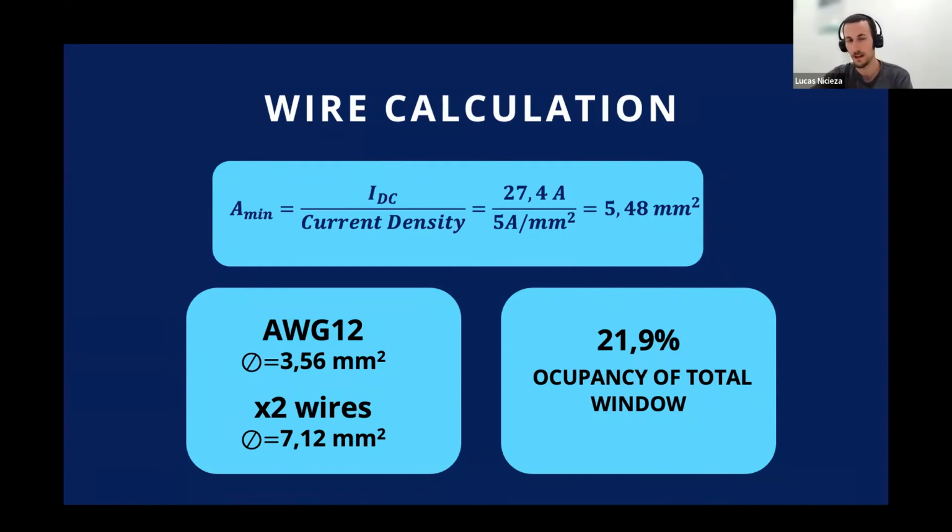The width is 2.5 mm. Then working with this wire is kind of, let's say, tough or complicated sometimes. Maybe not so easy to deal with in manufacturing. I mean, in the factory. So therefore, sometimes it makes more sense to go for 2 smaller wires, which is what we have done in this case. Also, in this story we have a low filling factor. So if we go for a single wire, we have an even lower filling factor. But if we go for 2 parallel wires, we can increase the conduction area and reduce the losses of our component.